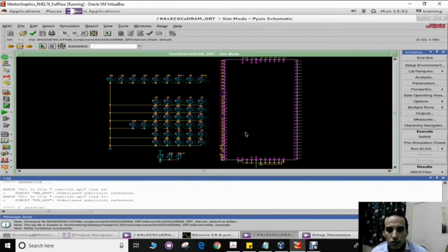So we can make sure that this is the worst case data retention time, and all the clock signals are used as 1 microsecond to make sure that the data retention time is due to the decay, not because of the incomplete write operation.